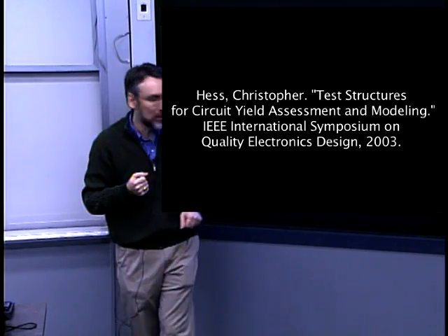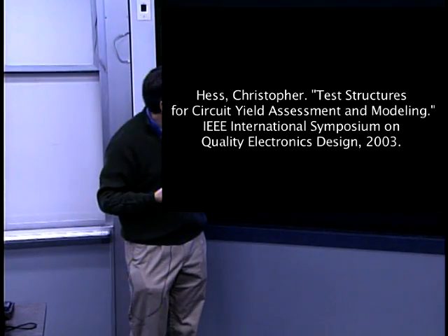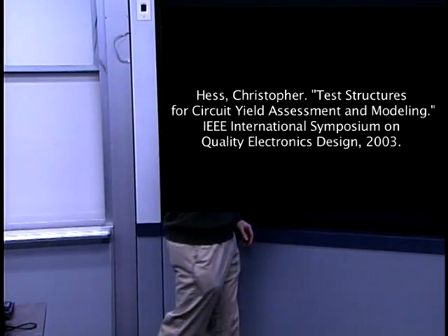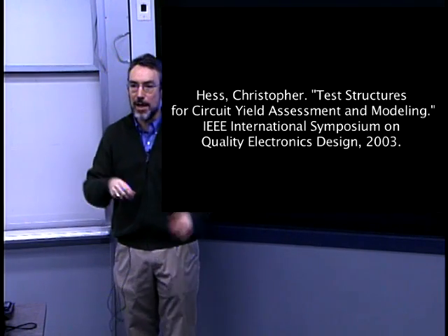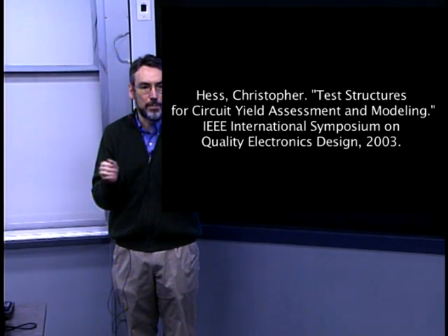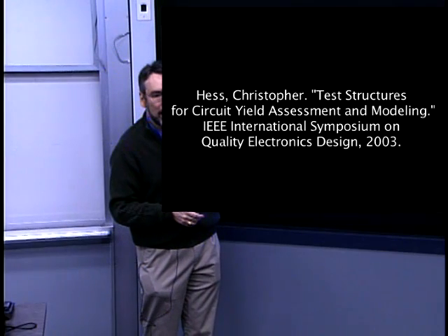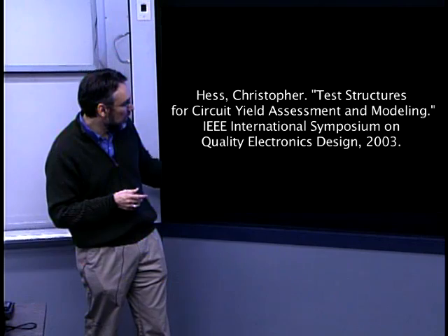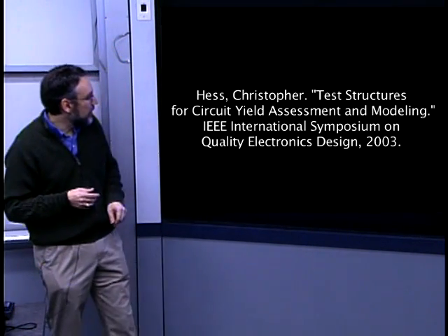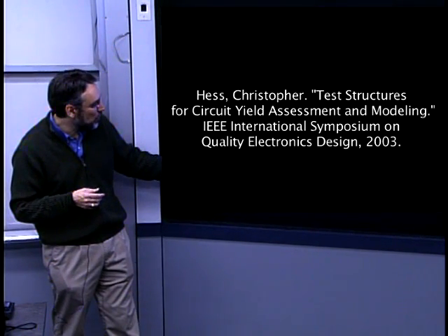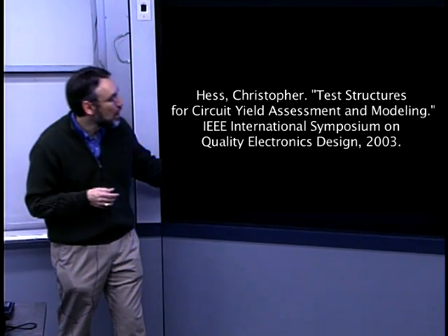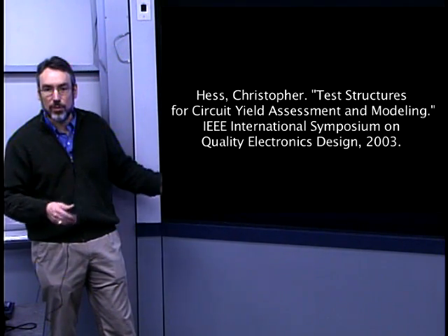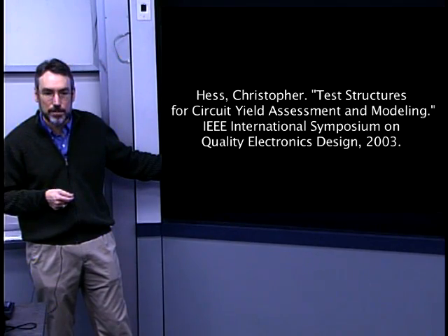And you can also use this structure to characterize the size of these defects, especially if they're relatively large. So for example, if I had a big particle that bridged 3 of these lines, I know within certain bounds that I've got a particle between some size interval. And so that's what's shown over here is kind of a defect count as a function of the size in microns of different particles for these large area sampling structures.